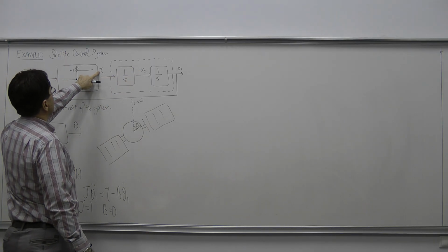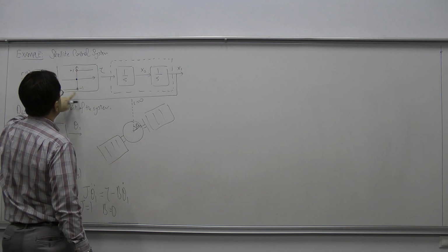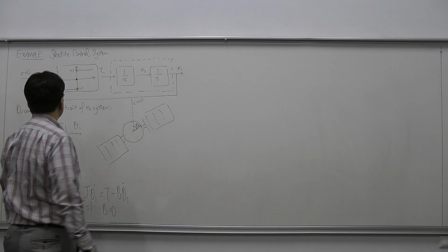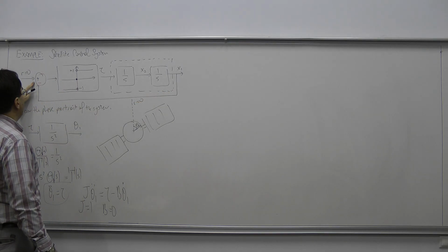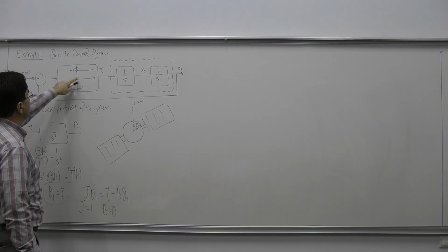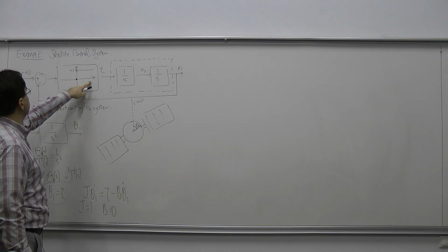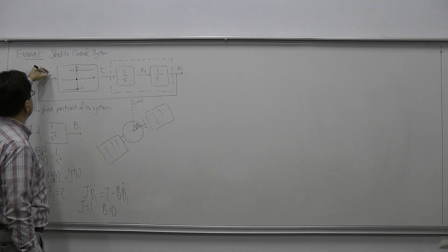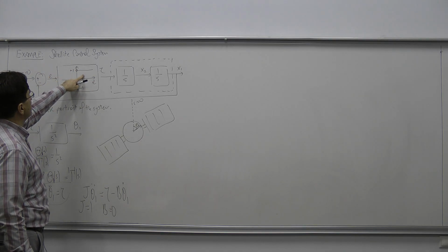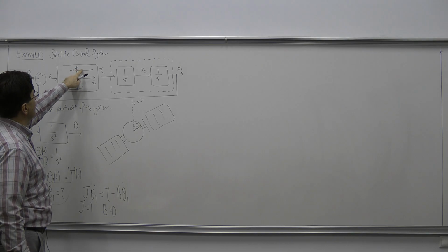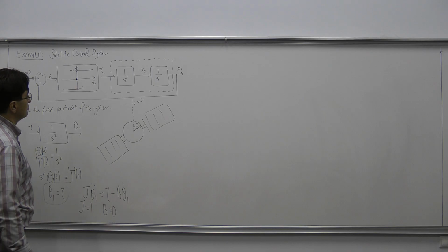The torque that is applied onto the inertia is given by a sign function. We first calculate an error, and if the error is positive, we apply a constant torque independent of the magnitude of the error. So this is the error here. Independent of the magnitude of the error, we always apply a constant torque 1 here to the inertia.